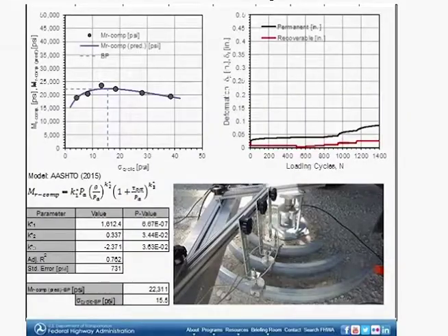So we have an approach. Now what we've been doing in the field is we've been measuring the in situ composite resilient modulus and calculating layer resilient modulus values for stresses. And one of the complicating things in the field when you test aggregate materials over subgrade is you get these really interesting stress dependent curves.